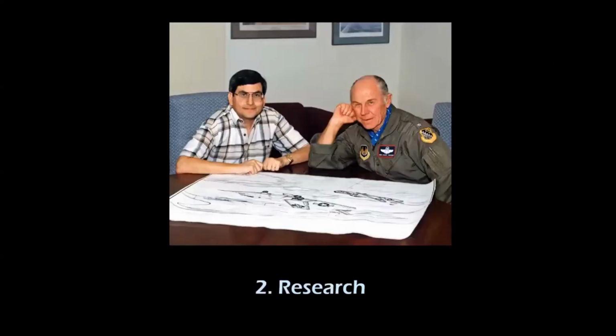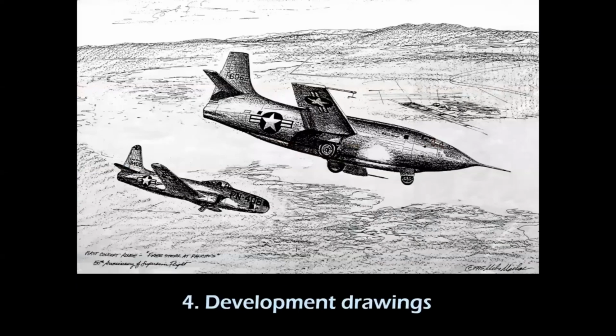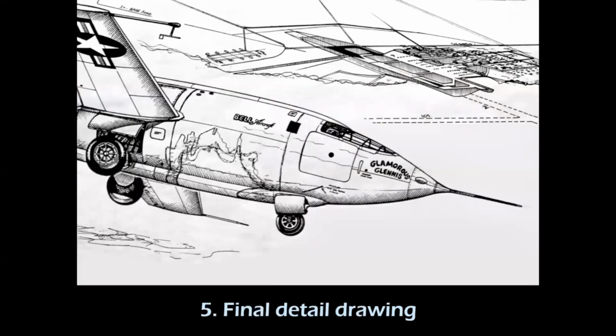Care and use of drawings. Drawings should be handled carefully as they are both expensive and valuable. Open drawings slowly and carefully to prevent tearing of the paper. When the drawing is open, smooth out the fold lines instead of bending them backward. To protect drawings from damage, never spread them on the floor or lay them on a surface covered with tools or other objects that may make holes in the paper.